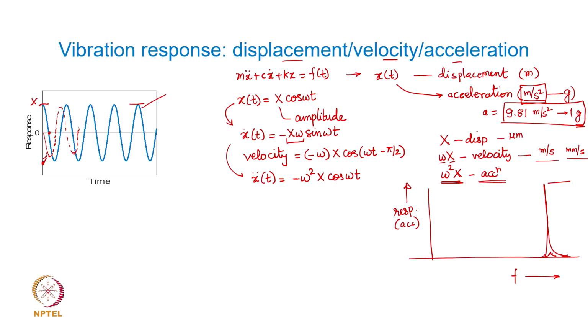and that is because of the vibratory displacement, even if it is very small in amplitude. The very fact that acceleration is omega square times x means a very large value of the frequency. For example, if we are talking about 4 kilohertz or 3 kilohertz of frequency, multiplied by 2 pi, that gives you radians per second.